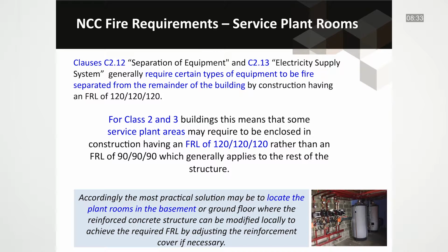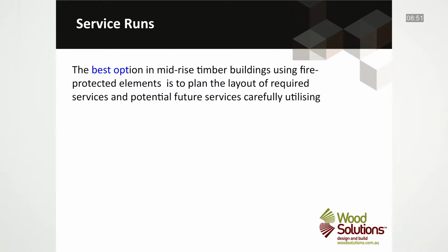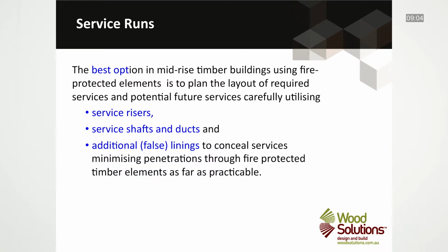Accordingly, it is often the most practical solution to locate the plant rooms in the basement or ground floor, where a reinforced concrete structure is often used, which can be modified locally to achieve the required FRL by adjusting the reinforcement cover if necessary. Service runs are also a really important concept. The best option in mid-rise timber buildings using fire-protected elements is to plan the layout of required services and potential future services carefully, utilising service risers, service shafts and ducts, and additional false linings to conceal services, minimising penetrations through fire-protected timber elements as far as practicable.